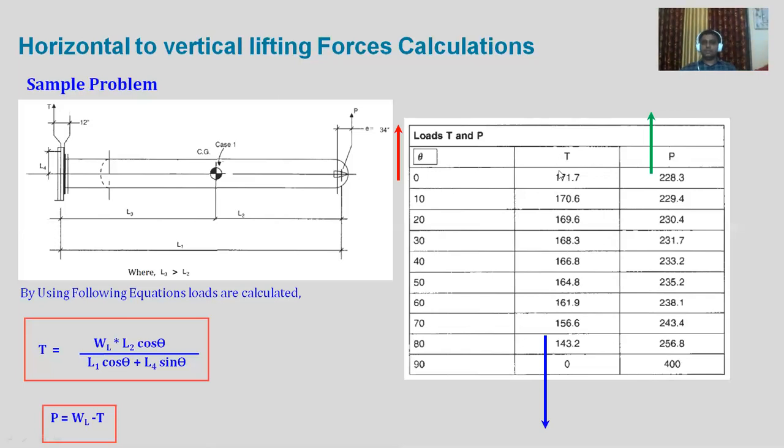So usually in this the worst value will be taken, and in this the worst value will be taken, and for that worst, which will be a hypothetical situation, we will design it, and if it is safe, then we can say there will be no condition at which it will fail. Otherwise, for each and every condition you need to calculate the stresses separately.